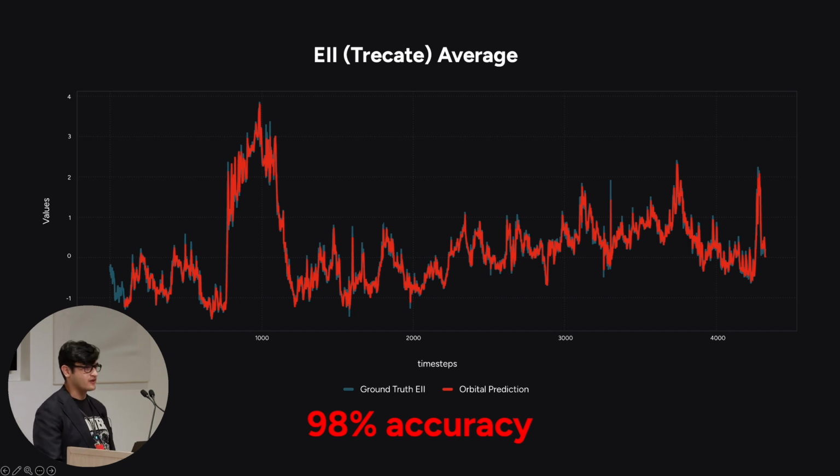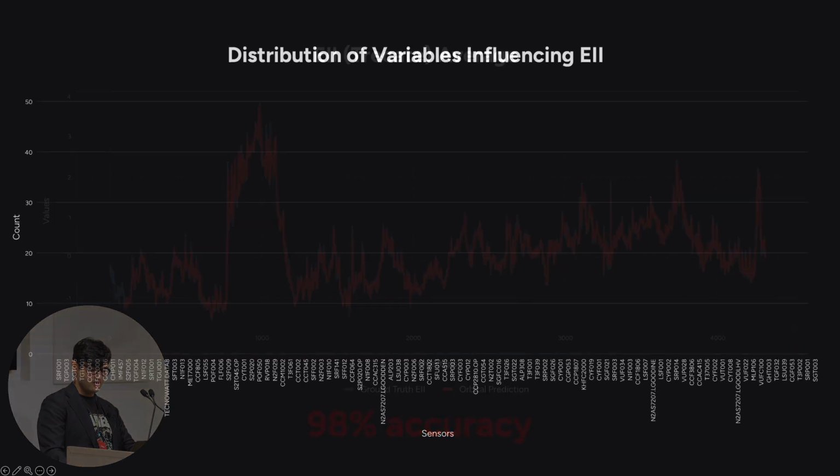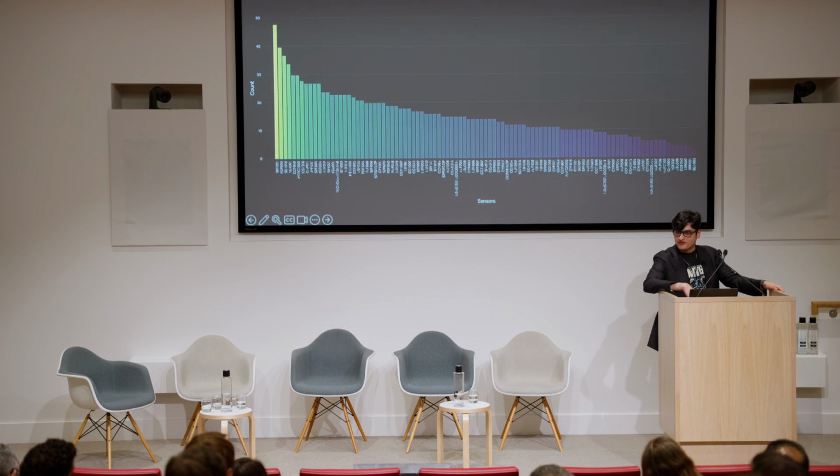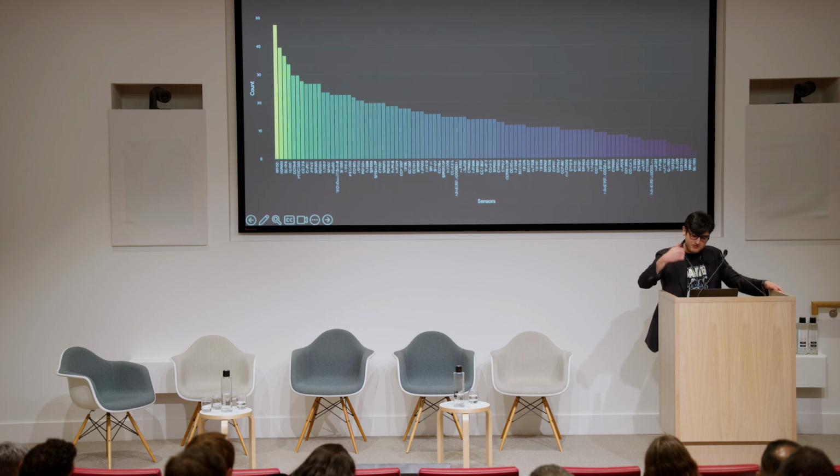And because it learned that correlation deep within the embedding matrix of the model, to estimate how sensor data from equipment relates to the energy intensity index, we were able to create a plot showing the biggest influencing factors to the energy intensity index, directly tagged to the actual equipment itself. And just by targeting the right equipment in order, which was a top 20 in this case, they were able to identify exactly why the energy spiked and what part of their plant was running inefficiently, to be able to maximize high octane yield, reduce fuel gas, and reduce steam makeup.